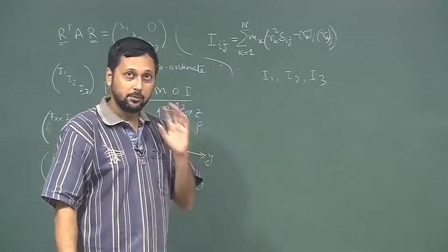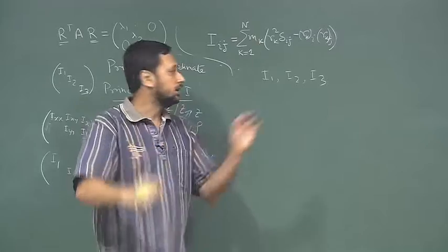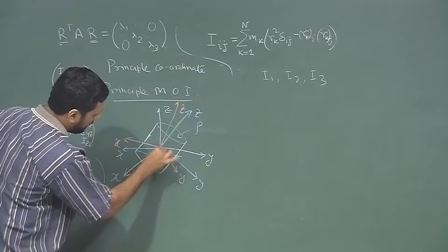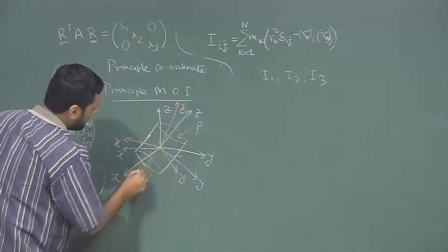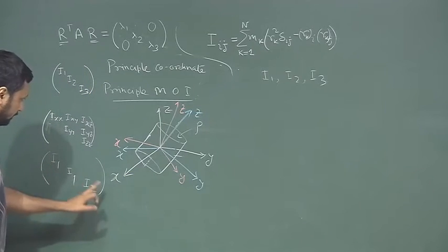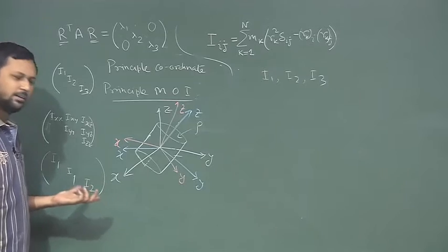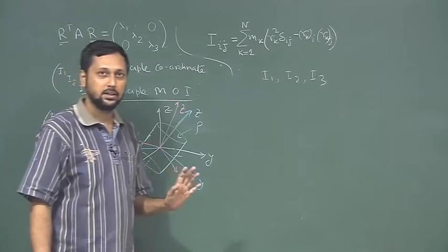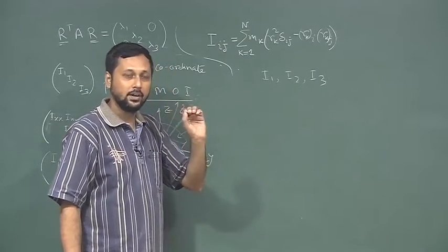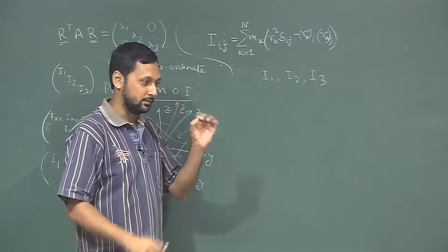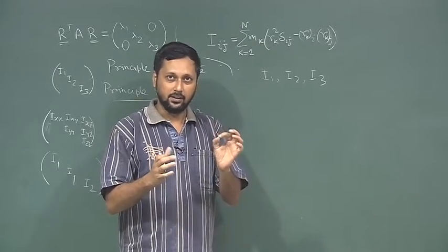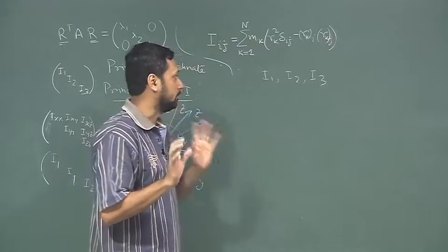But please again keep in mind that the moment we change the origin, your I1, I2, I3 will also be changing, right. Even here, if I am shifting my origin from here to here or some arbitrary position even along this axis, okay, my I1 and I2 values might change, not might, definitely they will change, they have to change, right. So, whenever we are talking about principal axes, we have to have a fixed point. So, the rigid body is rotating keeping one fixed point in it, and that fixed point is our origin all the time, please keep that in mind.